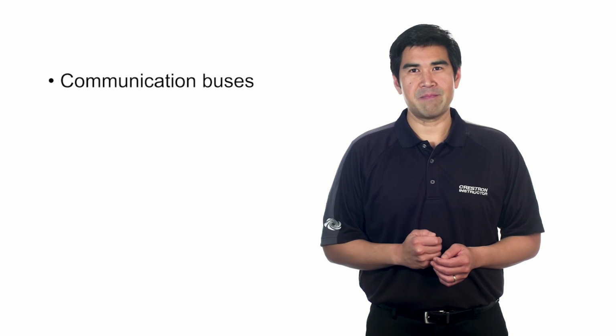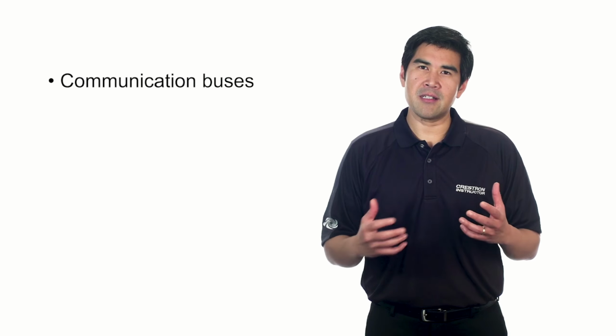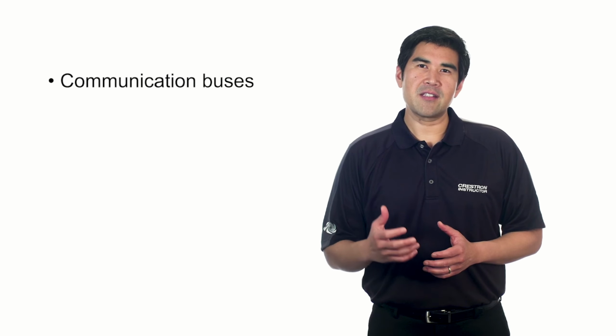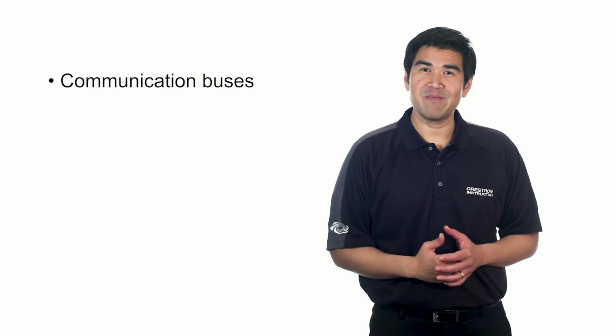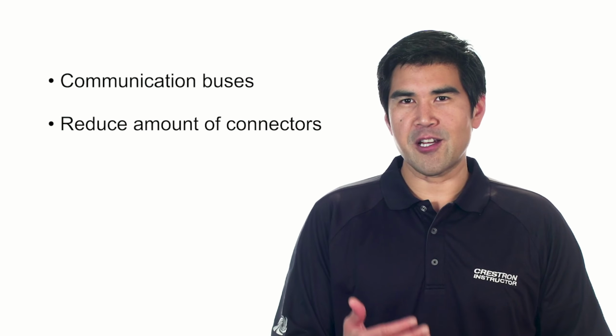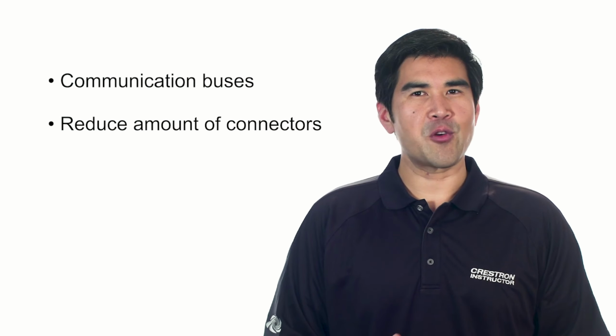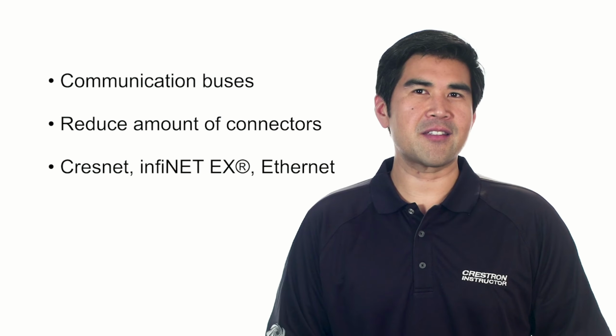As we have seen, some communication types require single connection to each device, while others allow multiple devices on the same connector. These we call communication buses. A communication bus is a system that transfers data between components in a system. Devices on a bus communicate with a control processor and, in some cases, each other. Using communication buses reduces the amount of connectors we need, as one connector can communicate with many devices. In a Crestron system, there are 3 common buses: CrestNet, InfiniteEX, and Ethernet.